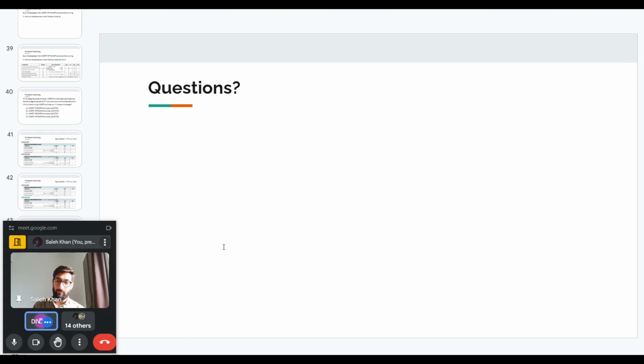And sir, that means IGBT is a unipolar, unidirectional device, and MOSFET is a bidirectional device. Yes, the IGBT by itself is a unidirectional device. But if we add a diode, so in circuits that you see, both can conduct in both directions.